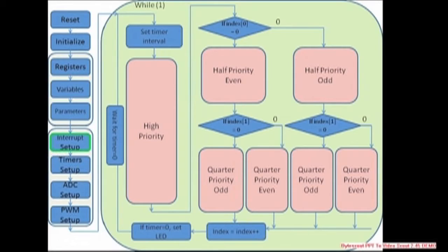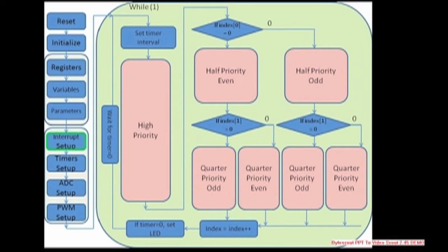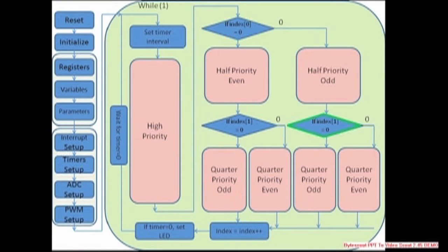Our firmware is a real-time exec. Shown here is the flow diagram. On the left is the reset and initialization control path. We initialize the processor, memory, timers, A to D converters, and PWM units, or pulse width modulators. The PWM units control the motors. We start up the exec called main, and the exec sets the real-time execution intervals by programming one of the timers. We are using 1/50th of a second for these intervals.